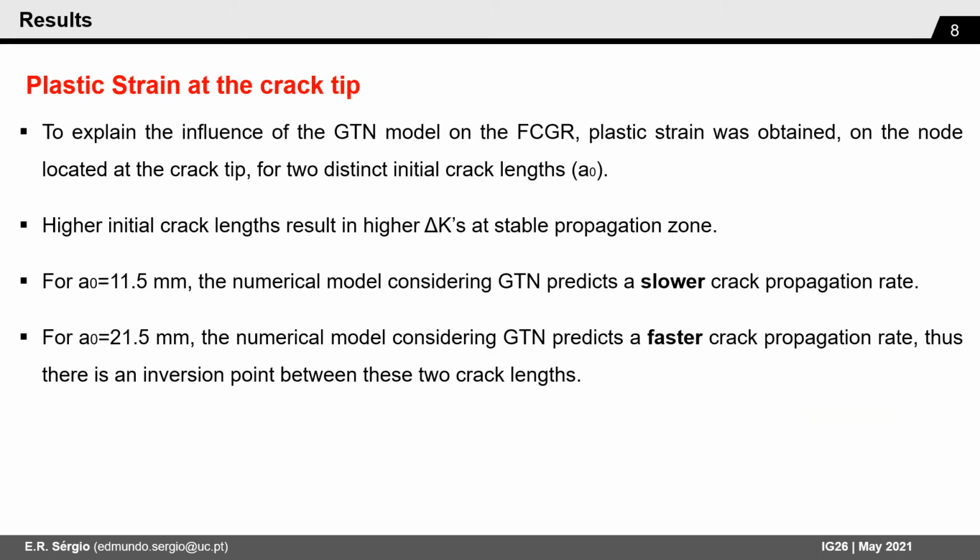To explain the strange protective behavior induced by the damage model for lower values of ΔK, the plastic strain was studied on the node located at the crack tip for two distinct initial crack lengths. Please note that higher initial crack lengths result in higher ΔK values when the stable propagation zone is reached.